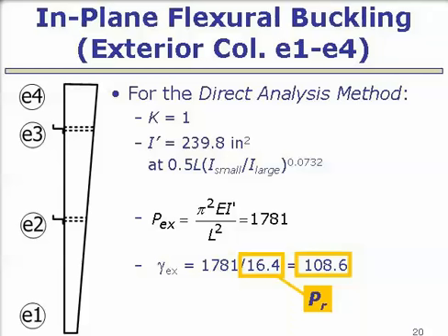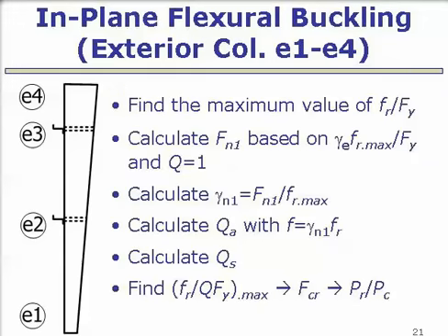Okay, 16.4 is the required axial resistance. So not a lot of axial load in these types of frames, right? Giving us the 109. All right, so now that we've got our gamma, the other part of this mapping that Yunduk had described is we want to look for where's the maximum value of FR to FY, probably at the base here.